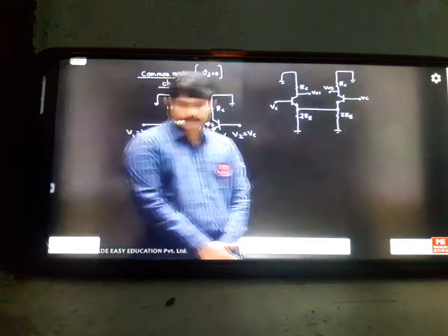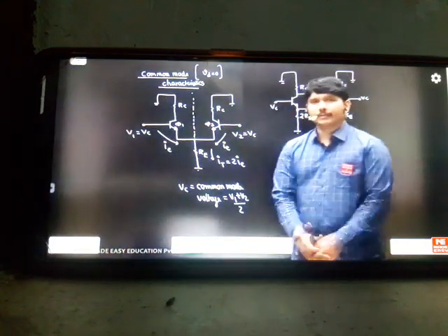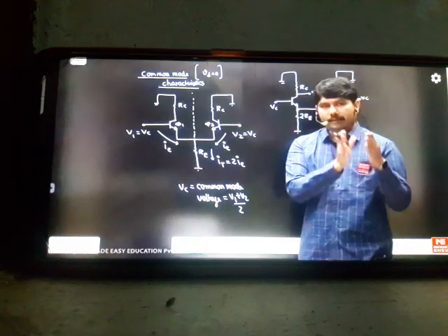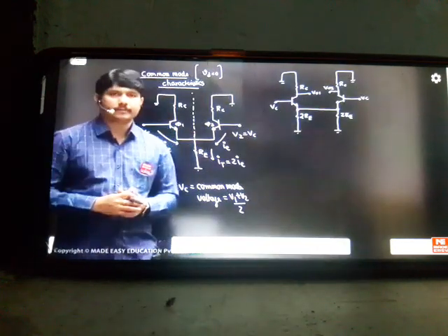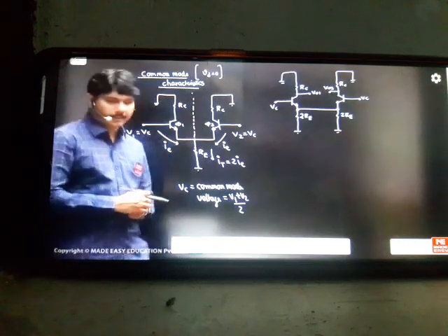Yashwant, why we call this unbalanced gain? Unbalanced gains, why we call A1, A2, means because we are taking only a particular output for one transistor. V01 is one transistor's output. That's why it's called unbalanced. Balanced means for both the outputs, if we take V01 and V02, then we'll call it balanced. These are the things yesterday nicely explained for you in the class.